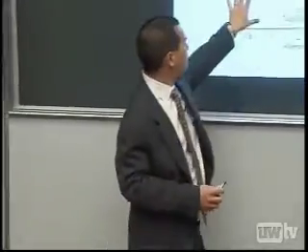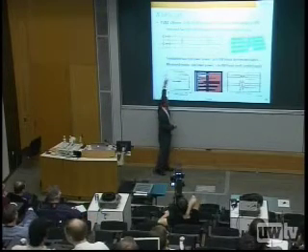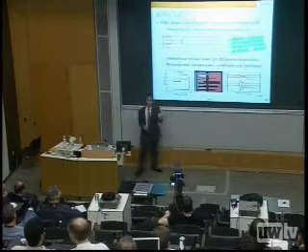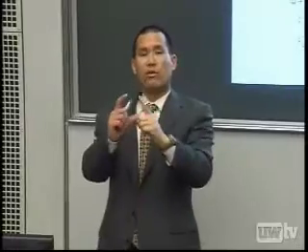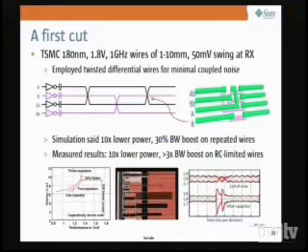In simulation, this is a plot of the performance versus the energy. So you want to live down to the right, sort of high performance, low energy. And if I'm driving a 1 centimeter long wire with a single driver, like a single stage repeater, I can vary the driver's size and trace out this curve, one repeater curve, in energy performance space. Not a lot of variation. If I use 2 drivers and broke it in half, I get a larger curve, so you probably want to live about here. But the capacitive driver was in fact quite a bit faster and a lot lower power. It lived down here. Okay? So in simulation, it seemed to be interesting.